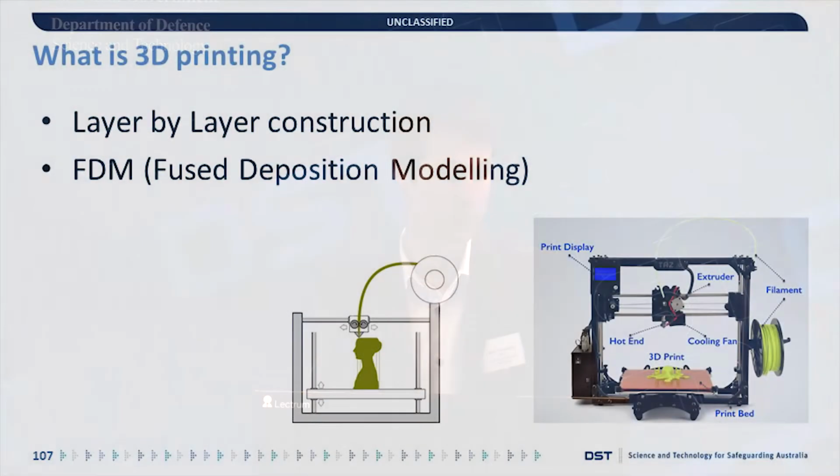Hello everyone. So I'm going to be talking a little bit about 3D printing using a robot arm. The most standard form of 3D printing is FDM 3D printing, which stands for fused deposition modeling. The way it works is you heat a filament in an extruder, and the extruder moves around depositing material layer by layer until you build your object.